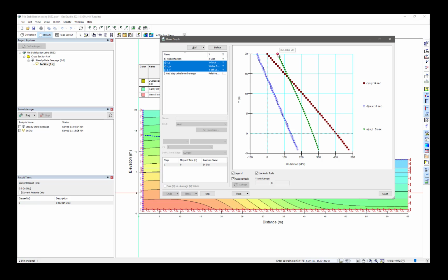It's 61 kPa, which is the opposite, the positive sign, of the negative pore water pressure. So again, by not including a volumetric water content function, we've artificially increased the effective stress in the unsaturated zone to equal the negative pore water pressure.